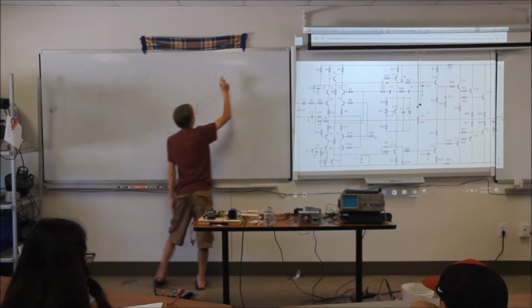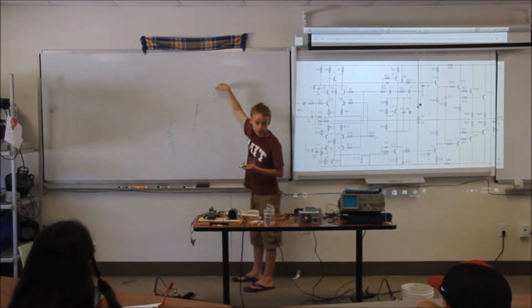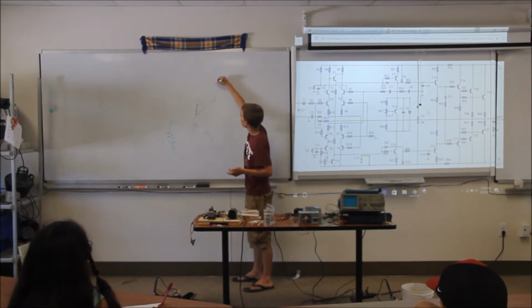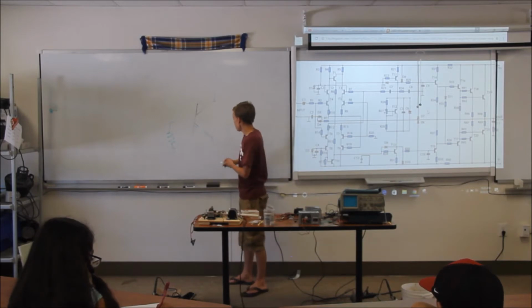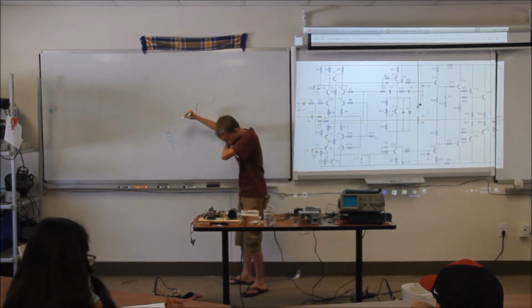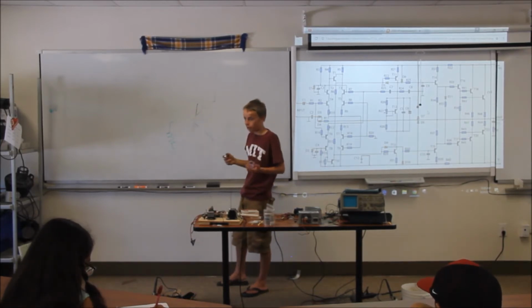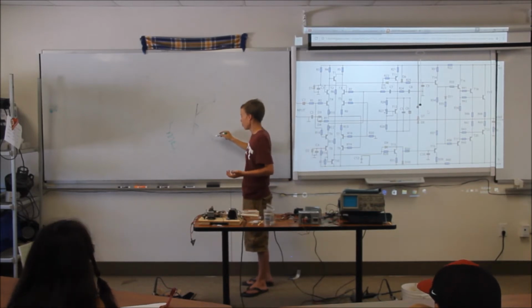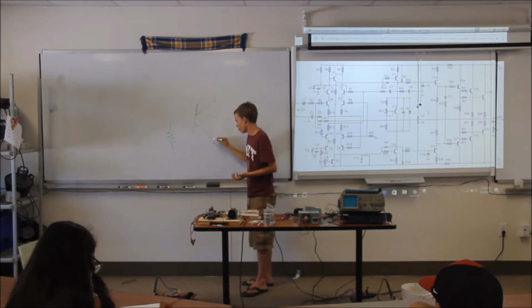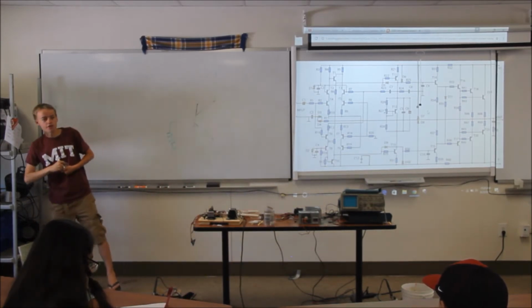So the current in this circuit will actually need to be switched, because we can't put the actual circuit that's going to be drawing the current out here. We'll have to put it down here, which means that the current will flow through the collector through the base into ground. That will turn on the transistor, allowing current to flow through the collector, through the emitter, and back to ground, through whatever circuit you want to run it inside. And so that is how a PNP transistor works.